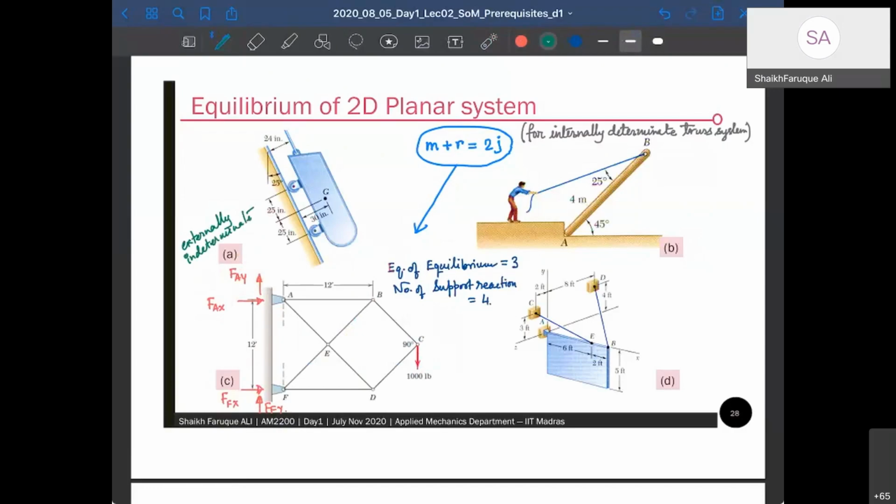And what about internally? You remember that some of you, I think Kanikeshwar or someone, told that a truss has to have a triangle, right? But can you see that thing is missing somewhere? It is missing here. This is not a triangle. So internally, it's not stable. But if you combine both internal and external, it's a very stable truss and you can solve it.